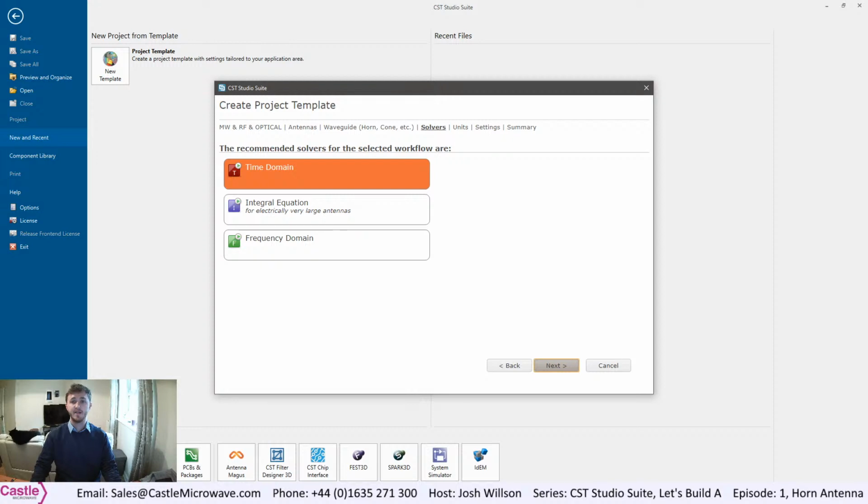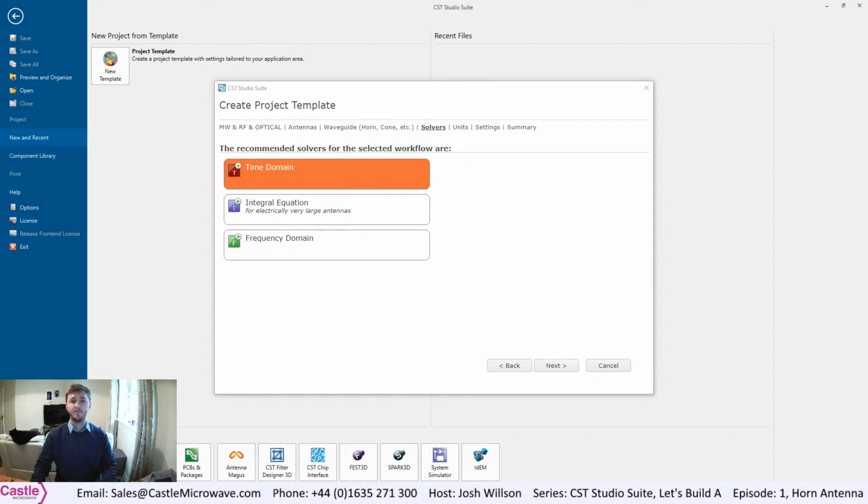Therefore, the denser the chosen grid, the smaller the usable time step width. This means that a high mesh resolution of a small detail inside a given structure possibly determines the global time step and therefore the total simulation time.